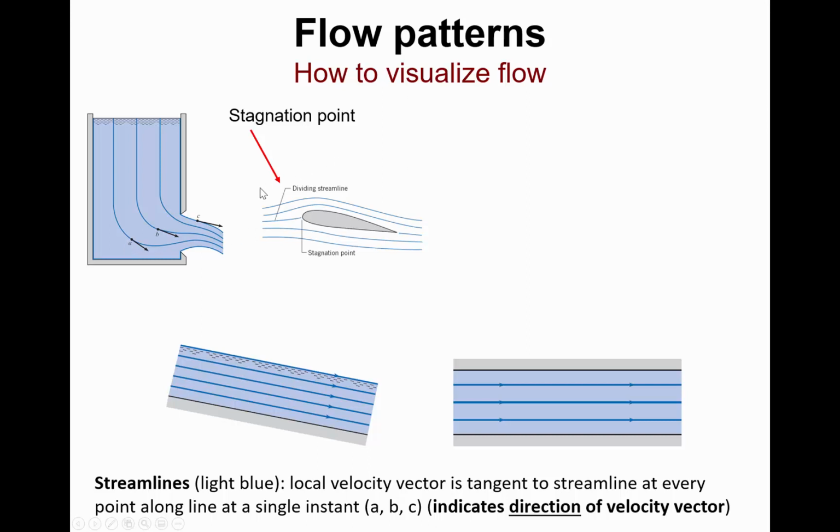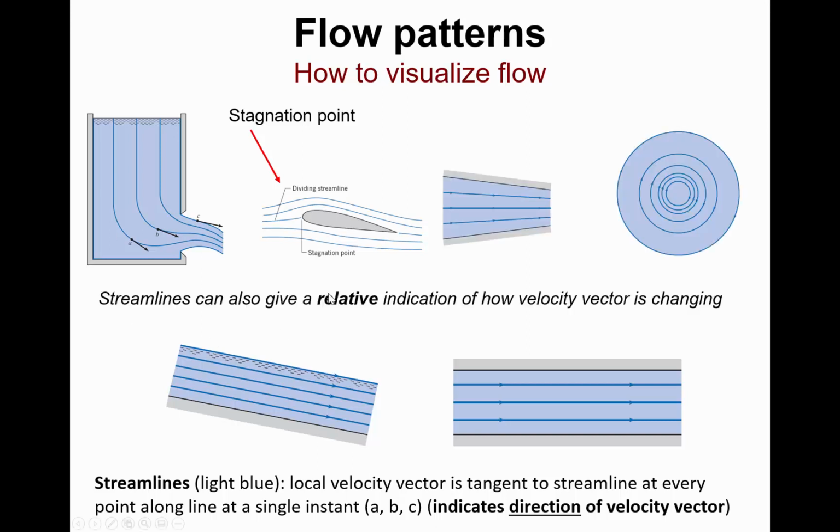Now, in the case of the streamline that's encountering an airfoil, there's this one streamline that dead ends, and it stops at the leading edge of the airfoil. And that stagnation point is going to be a location where the pressure increases slightly along the leading edge of the wing, because whenever you have a velocity vector that just stops, then all of the energy that existed as velocity is being transferred into an increase in pressure. And so that's what happens on the leading edge of the wing.